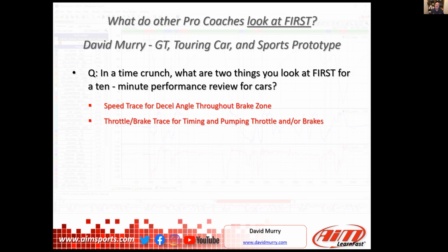Again, speed trace for the decel angle through the braking zone. This whole idea of the decel angle, the shape of the speed trace, conveys huge information. We'll talk about that again. If the braking is working right and the driver is executing well, the decel angle through the brake zone should be relatively almost linear in its decline. The throttle and brake trace is for timing and pumping of the throttle or the brakes. That indicates yes, no, yes, no.